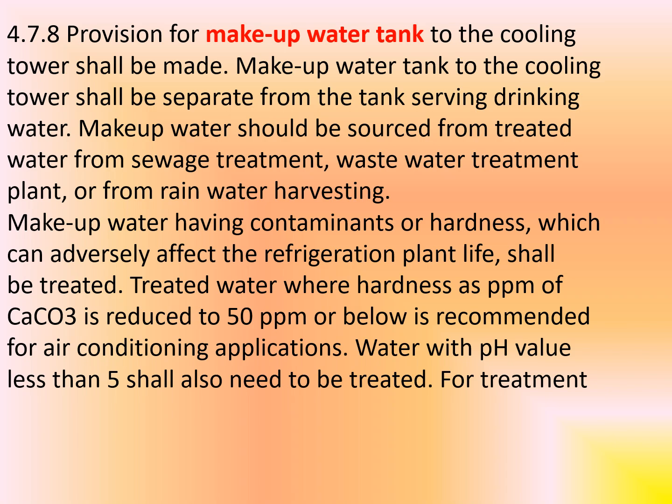Treated water where hardness as ppm of calcium carbonate is reduced to 50 ppm or below is recommended for air conditioning applications. Water with a pH value less than 5 shall also need to be treated.